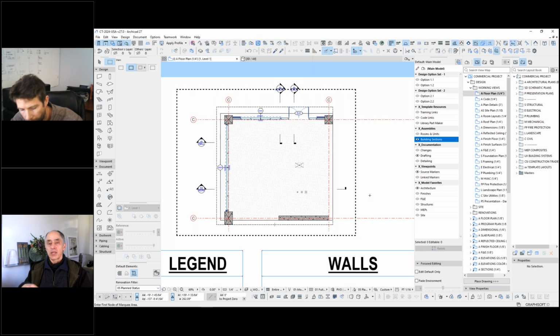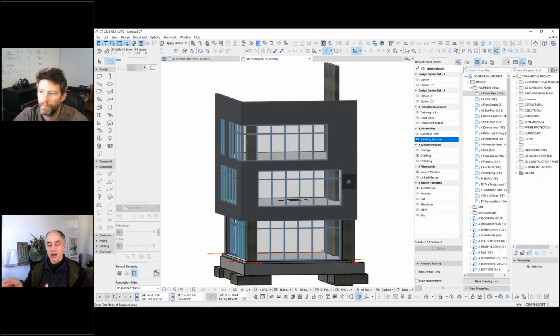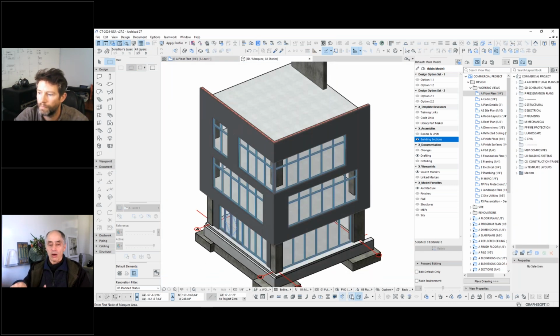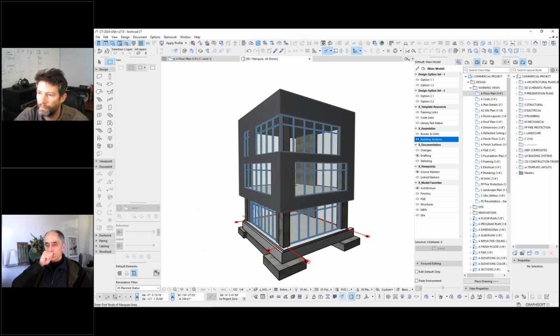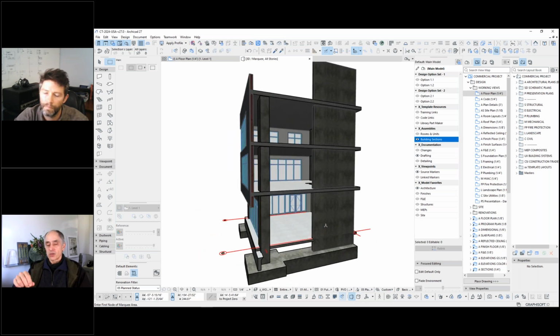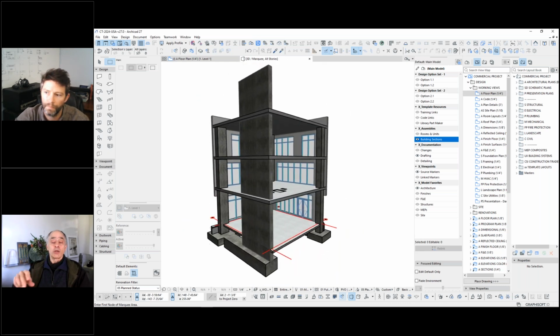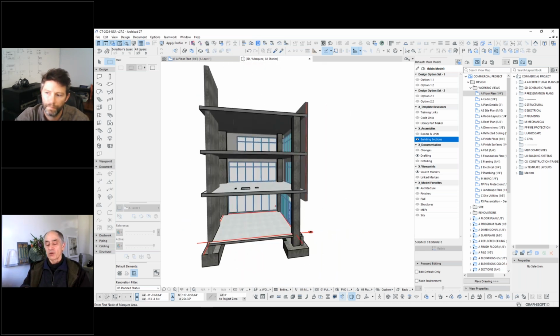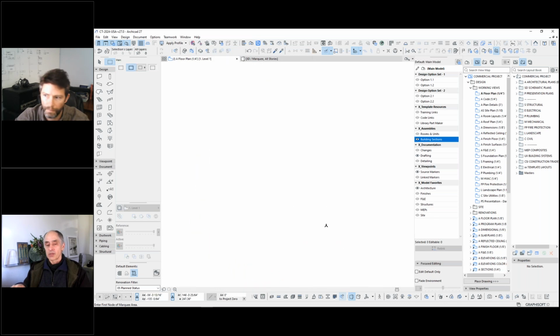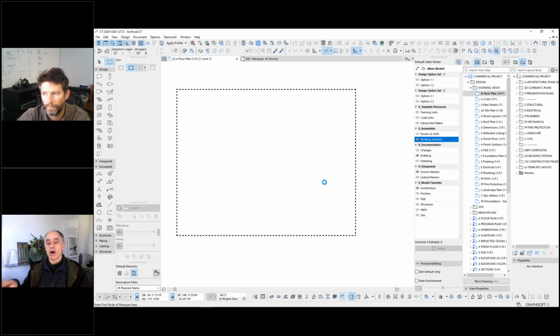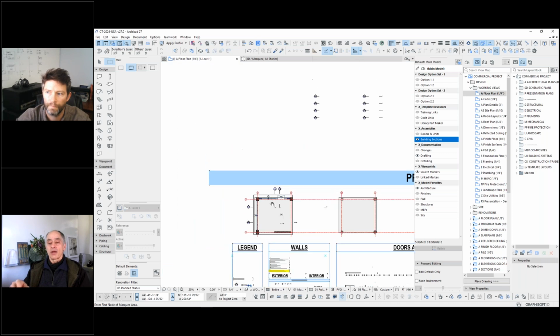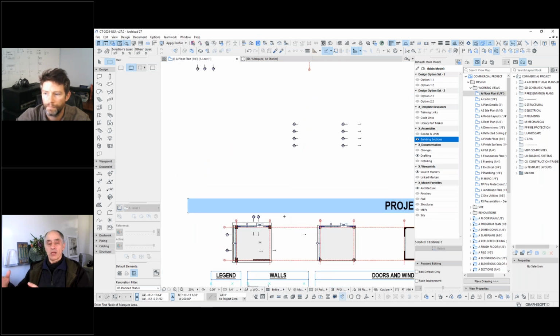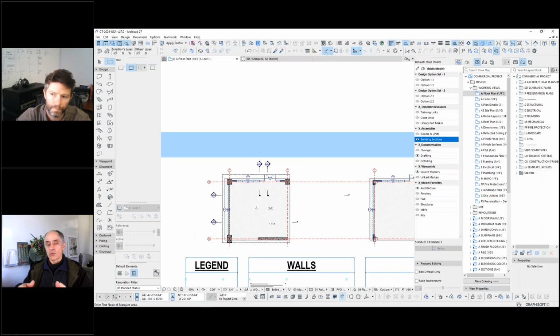Now, when you place something new, either dragging a copy or eyedropping and drawing, it will not automatically be linked to the same control, because it depends upon your setting, but the standard thing in the design options is that you're adding things to the main model, unless you tell it that I'm adding it only to scheme one, or option whatever.